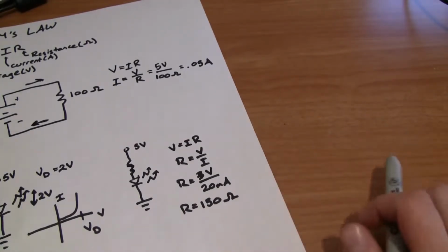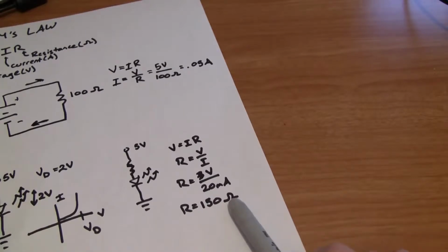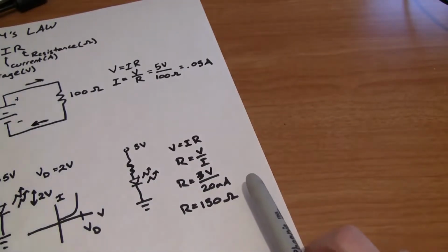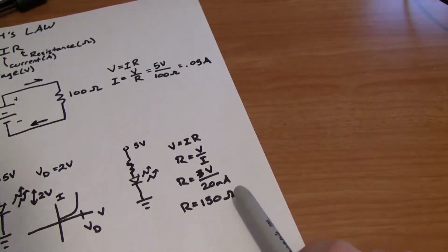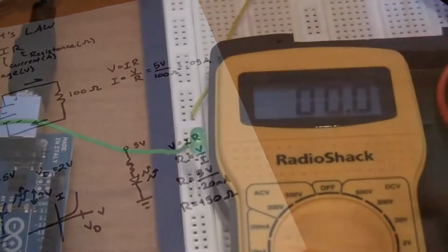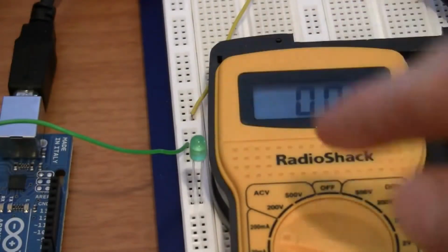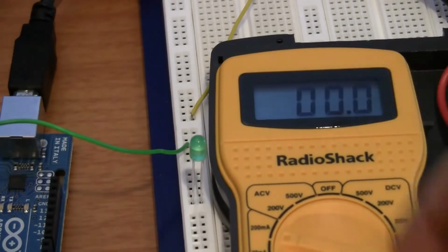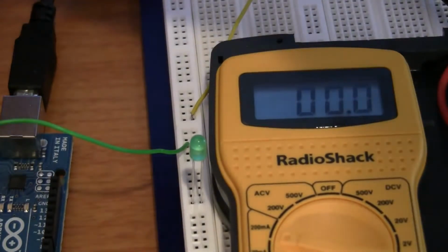And of course you can go higher than that. It'll make the LED a little bit dimmer. You can even go a little bit lower than that, but you usually don't want to go too much lower. You'll be drawing too much current and hurting your battery life. And that's it. So let's see an example of what this means in an actual circuit. So I have an LED here hooked across our voltage and ground lines from the Arduino, which is running at 5 volts. Let's see what happens to the current that's going through it when I plug it in.